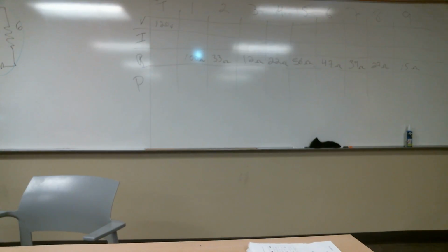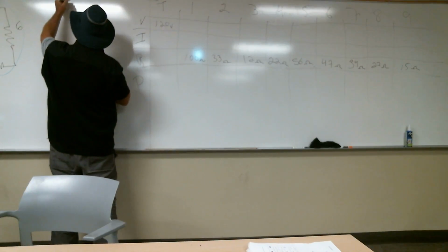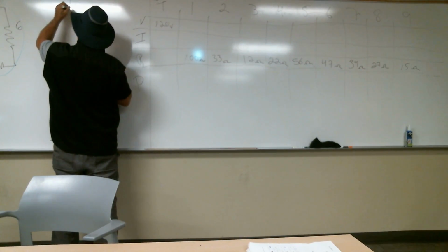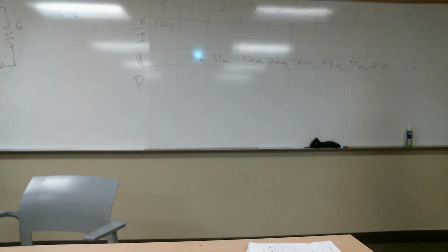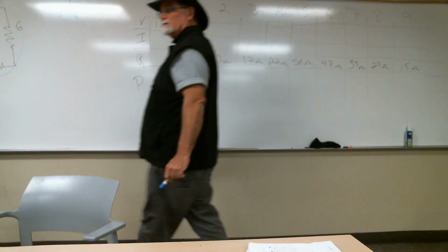However, at this point, I have a value that's the sum of 3, 6, 7 called 98 ohms, and that is purely in a parallel relationship with number 5, which is 56, right? So I can do that combining. So I've got to use my 1 over formula, 1 over 56 plus 1 over 98. Okay, I know it's going to be less than 56. Given that the ratio of those is 2 to 1, I'm going to say it's about a third of 56, which would be what, 35, somewhere in there? 35.6, is that what that all works out to?